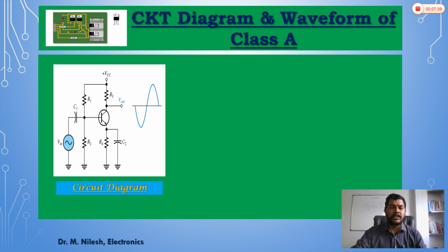Now the circuit diagram and waveform of the Class A amplifier. This is the basic circuit diagram of the Class A power amplifier, in which we are able to see that R1 and R2 are the base bias resistors to keep the base emitter junction forward biased. This is the input sine wave given to the base through capacitor C1, and R3 is the load resistance which is connected to the collector, and R4 and C2 are the emitter resistance and bypass capacitor.